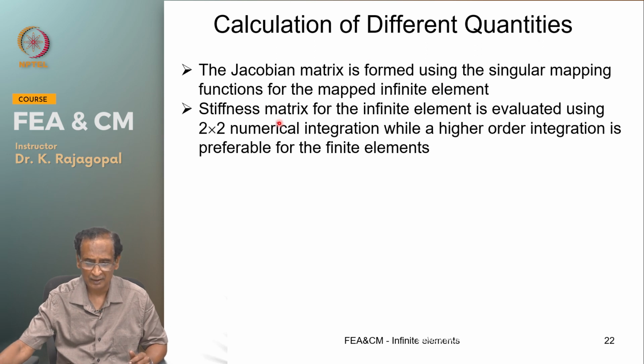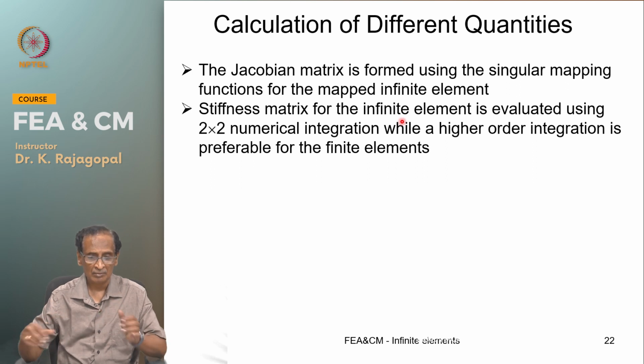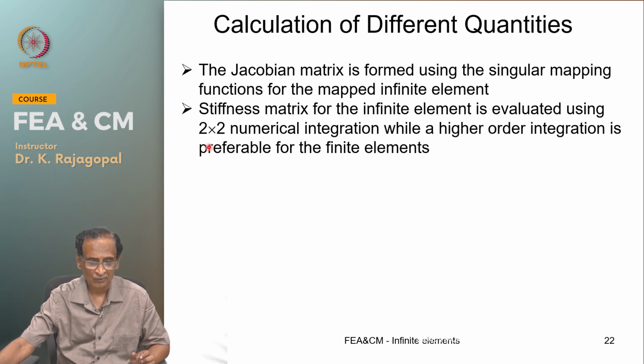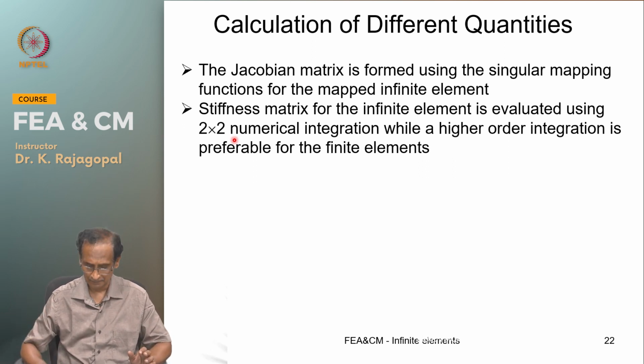Then our stiffness matrix is formulated using regular numerical integrations, and for the infinite elements we use a 2 by 2 integration, lower order of integration, whereas we use 3 by 3 for the finite elements.